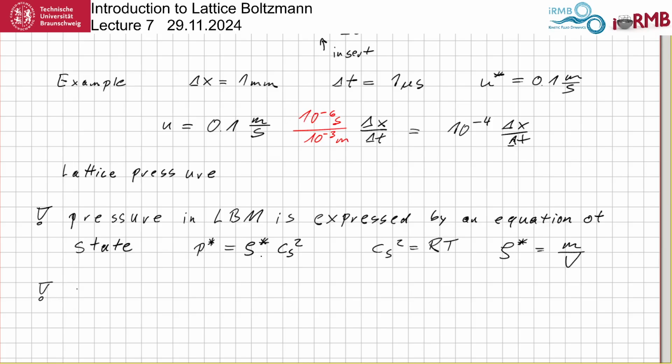The Navier-Stokes equation is a little bit different. In the Navier-Stokes equation, the pressure is a potential, and we don't care where it's coming from. And as a potential, you know how potentials work. They're only relative. Right? So you only care about the gradients, so you only care about differences in pressure, which is why in the Navier-Stokes equation, and this is another problem that newbies could run into when they implement, I've observed this many times actually, you could say that the background pressure is zero, because pressure is a potential, so you don't care about where your level of your potential is, right? Where your reference is, yeah.